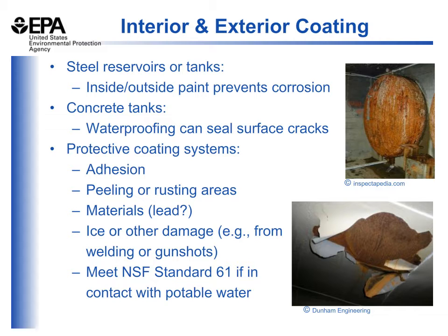So it's important to inspect both the exterior coating, as shown in the top picture, where the tank is clearly in need of a fresh coat of paint, and the interior coating, where problems can be less obvious. This interior coating will be in contact with your drinking water, so you should make sure it complies with NSF International standards. This inspection will ensure that the coating doesn't impart any taste or odor to your water, and that it doesn't release any harmful chemicals.